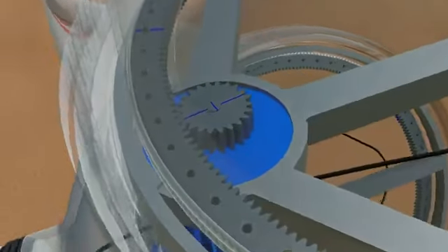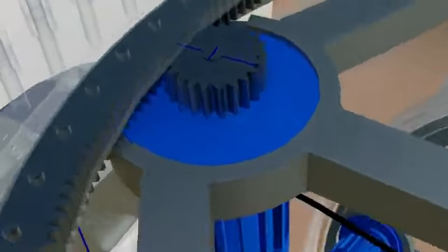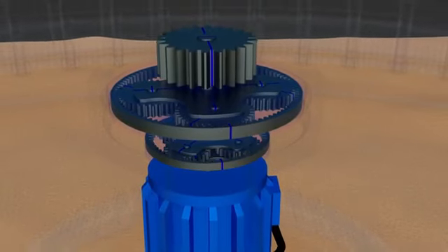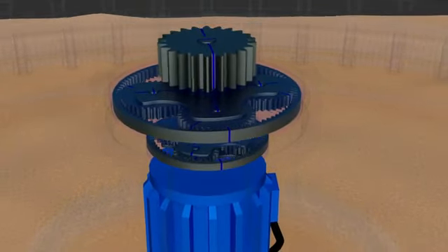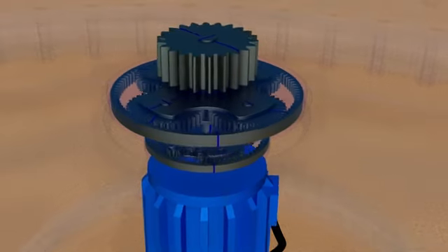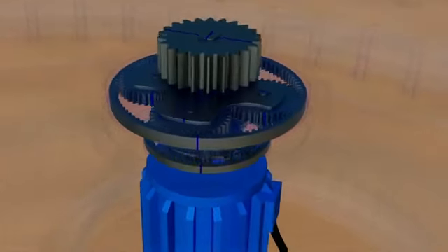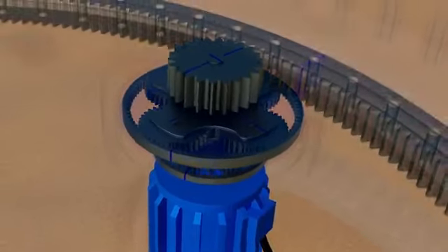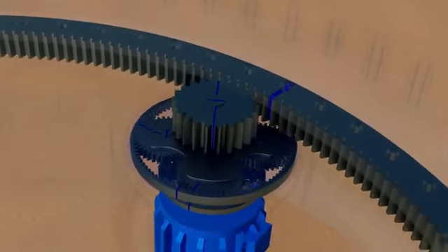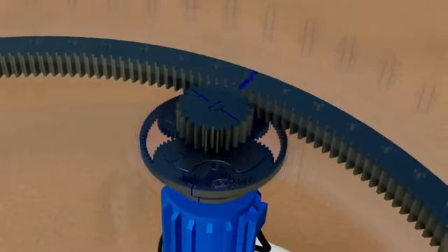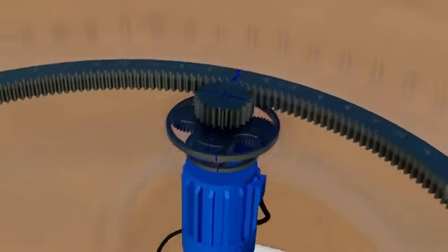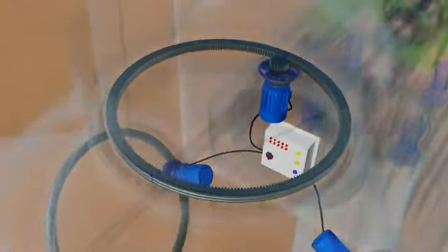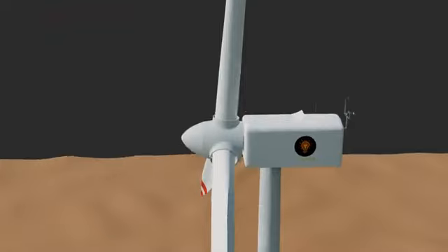However, its torque is insufficient on its own to rotate the massive blade against wind forces. A multi-stage planetary gear system is employed to multiply torque and reduce speed. In this model, a two-stage planetary system is used with individual reduction ratios of 5 and 6, creating a total reduction ratio of approximately 30. A large internal ring gear is then driven by a spur gear, providing a final gear ratio around 350. Pitch motors operate automatically depending on wind conditions, with each blade independently controlled for optimal performance and load balancing.